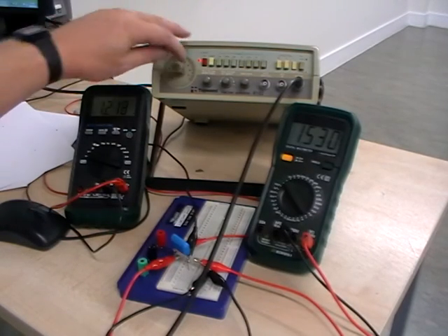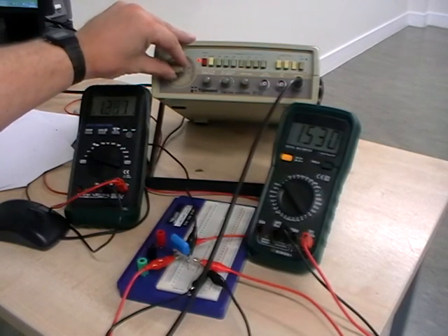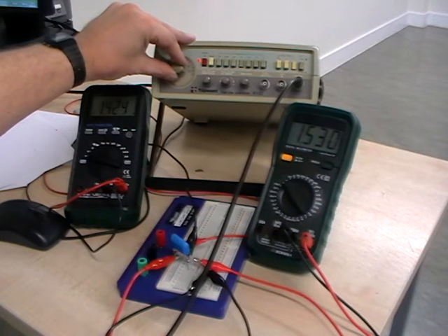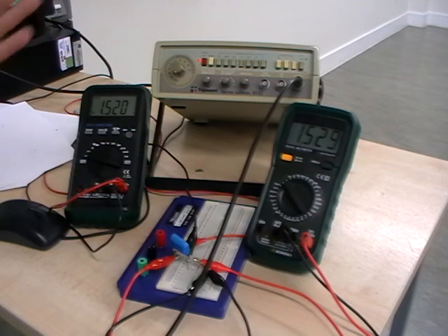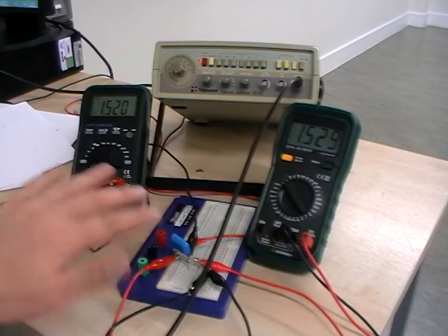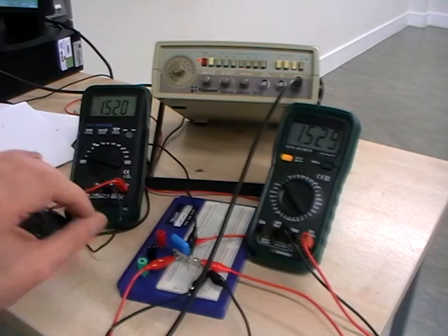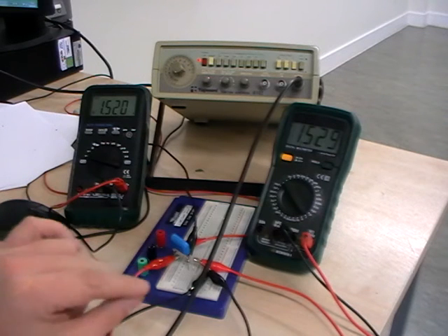And we are almost there. Let me just get it to half and half and see what frequency comes up. Ohm's law doesn't lie, signal generators do. So we are now at about 800 hertz according to the signal generator, and we've now got a ratio of half and half. So the capacitor has the same reactance as the resistor has resistance.